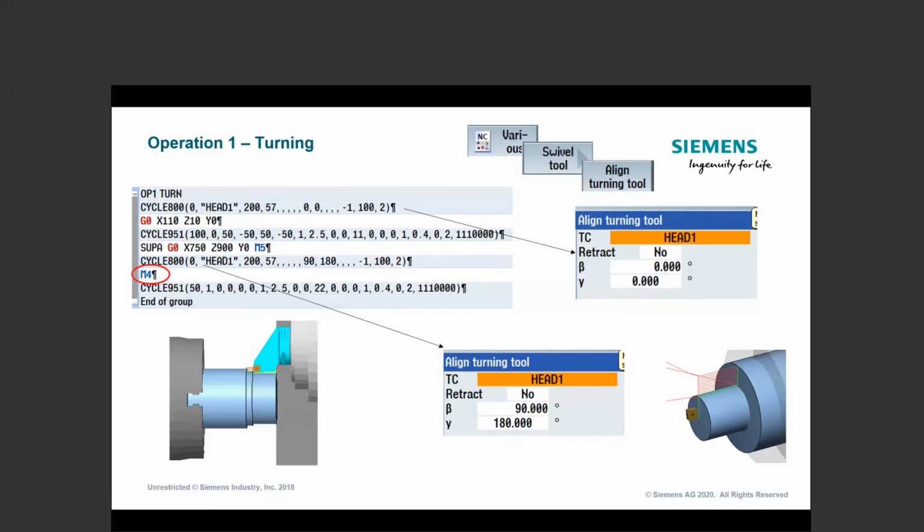It's at my 90-degree orientation, or however many cutting edges I had. Now, the one thing that the system will not know, because you're in G code, is if you have the spindle running the right direction. So that is totally on you. If you get your M3s and M4s mixed up, it will try to run.